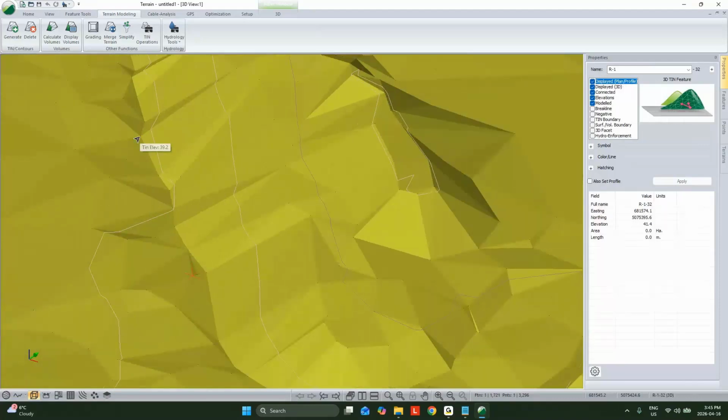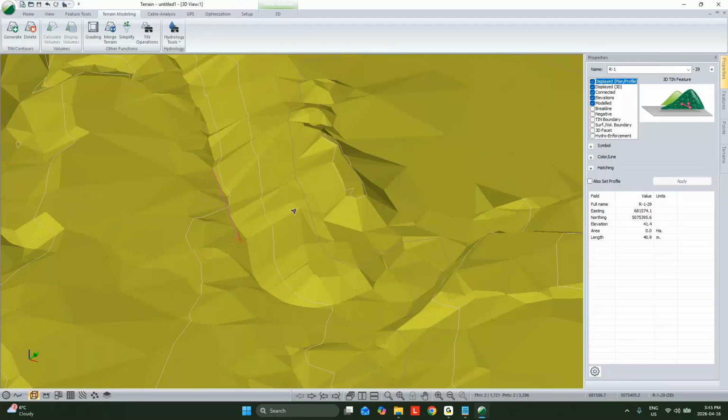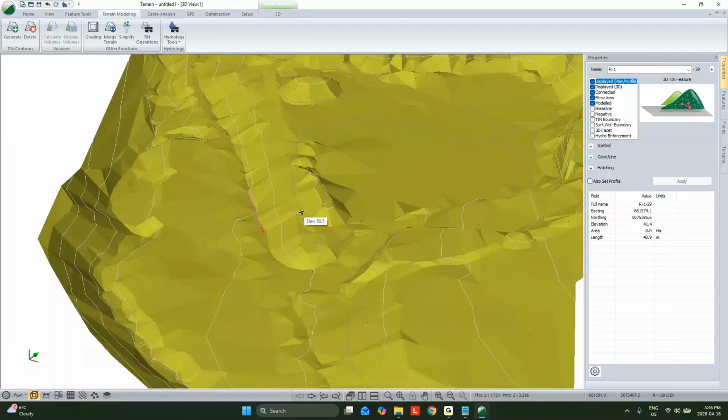That's probably a road edge point, and we can see the codes here, and we could hit Control J or feature properties join, and we could go through and play connect the dots. We can get to the same endpoint of the surface that we're working with, but it's tedious to play connect the dots and define all these polylines. It's especially tedious and frustrating if they were properly coded and there's a better way.